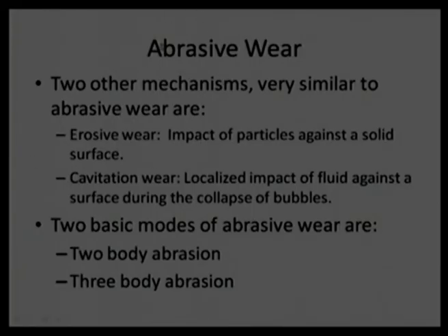So, abrasive wear is generally solid versus solid, but the particles are not coming with a high velocity, while in erosive wear we are talking about particles which attack the surface with a relatively high velocity. When we talk about cavitation, we are talking about a liquid which is making bubbles, or bubbles are induced in one way or another, and they get burst, releasing high pressure, and due to that pressure the surface gets damaged.